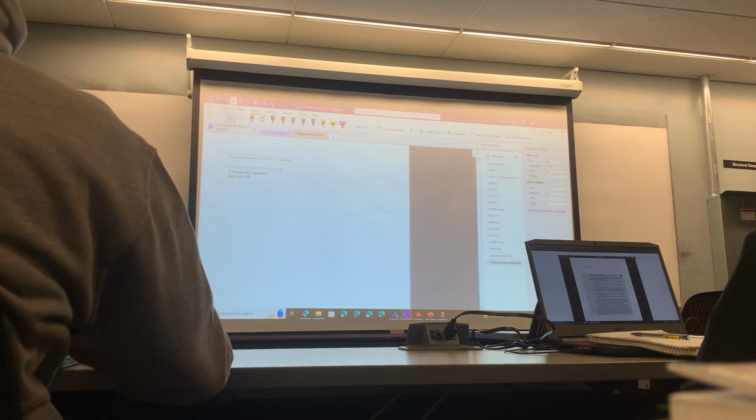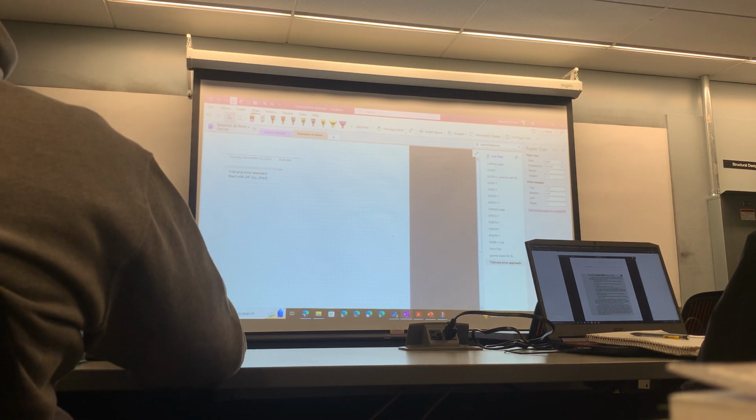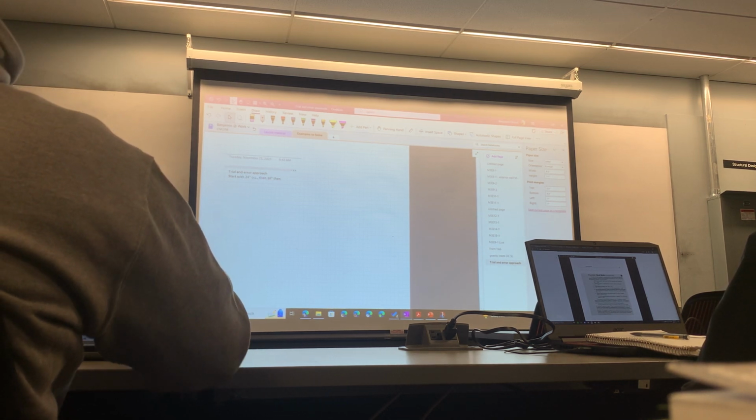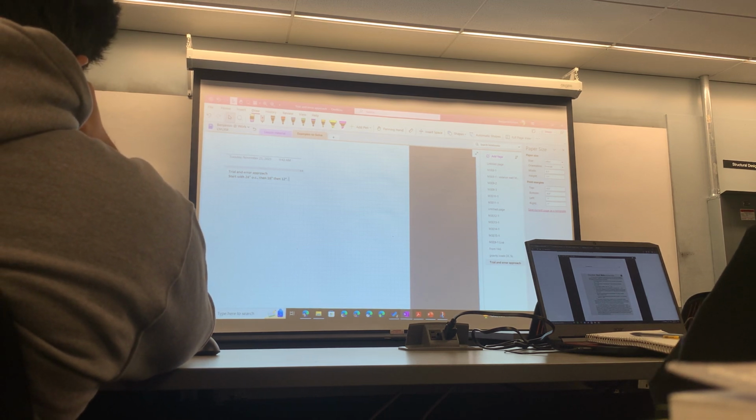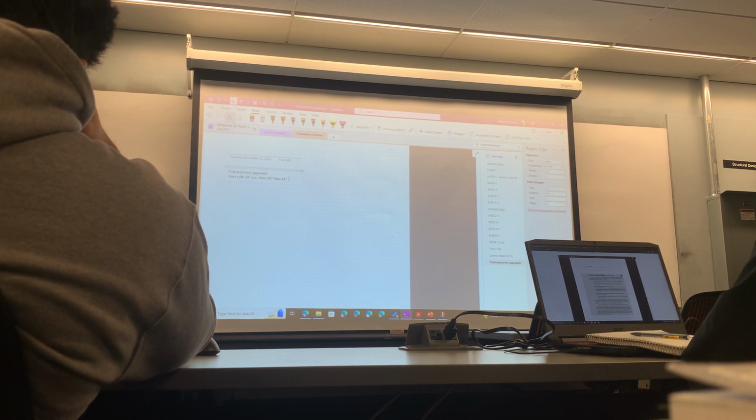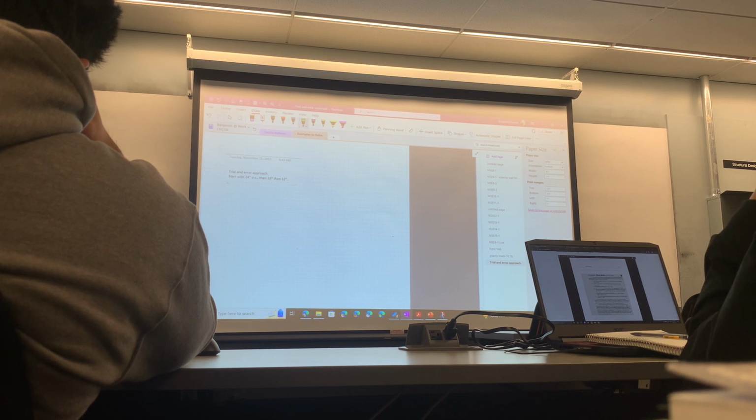Start with 24 inches on center, then 16, then 12. For this course we're doing 24, 16, 12. You guys know in industry we don't go greater than 16 typically. But the wood design manual does, so we're including it, and you guys can choose that as an option on your test. So let's start with 24 inches.